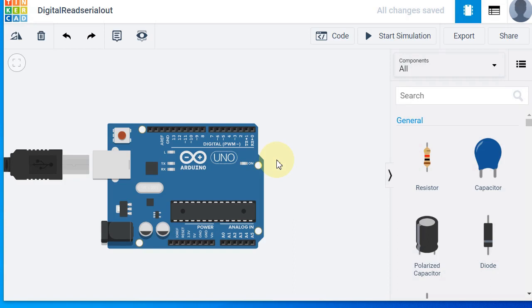In this demonstration, we are going to see an analog input by connecting a potentiometer. This potentiometer can vary from 0 to 5 volts as per the maximum and minimum voltage limits we are giving. Accordingly, we can vary the voltage range. So we are using this potentiometer as an analog input, and we are going to demonstrate how we can code the analog input, or process it, and get some useful output from it.